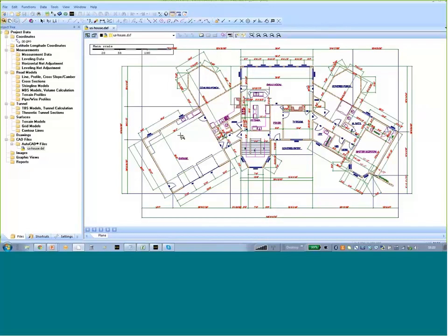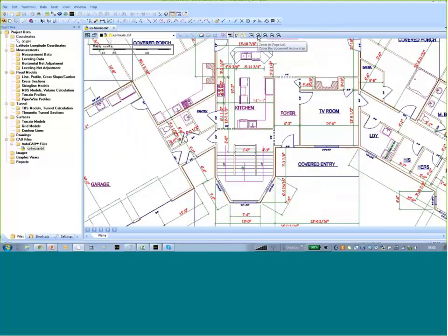I suppose the first thing to remember with DXF files is they can be large. They are very comprehensive in terms of the information they contain. Very large files with thousands of elements could create import issues within Icon. But for these really large files, there is an option within Icon Office called Clean for Field, and I'll go through that briefly. That's the only thing I really want to demonstrate here.